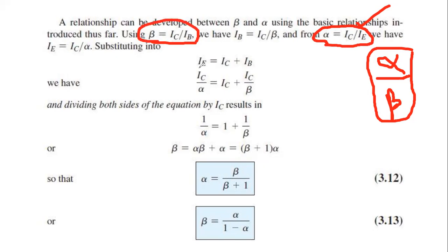And we all know that IE equals IC plus IB. This is a universal equation you need to know. You probably understand where it comes from, but I suggest that you memorize it, because if you don't remember it at that particular time, it will be very tough. So you need to know that emitter current equals the collector current plus the base current for all configurations and all types of transistor, either NPN or PNP. It is always the same.